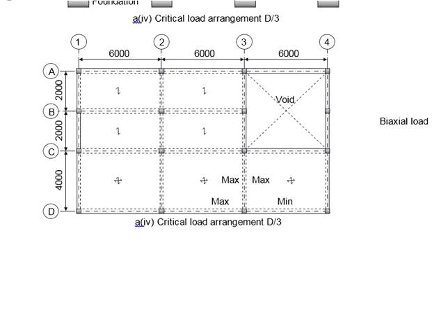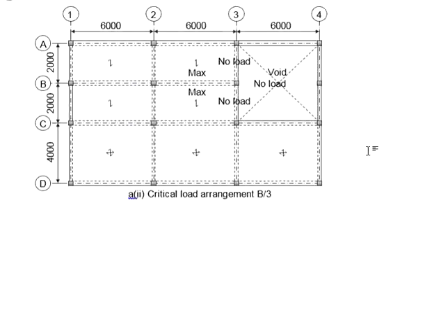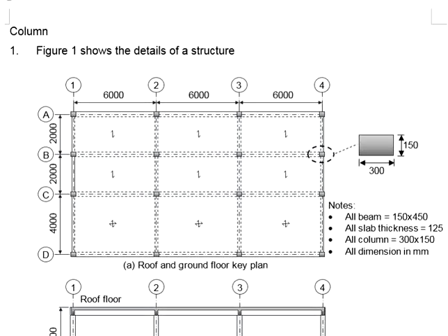or the minor axis. The main difference between bending in the major and the minor axis is the effective depth you later use to calculate the moment resistance of the column. The larger effective depth will give you greater resistance.